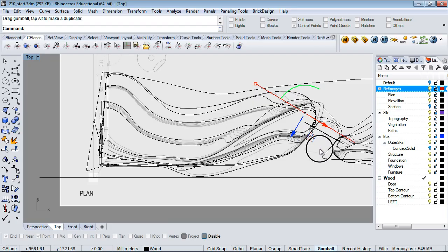Now that I know where the door is, I would be a little bit more careful about getting it parallel to the door frame. Then I would draw this curve and the start of this curve over here on the same plane. That way I have basically snapping points when I want to add the next geometry. I have a group of geometry there that I can snap to. Okay?